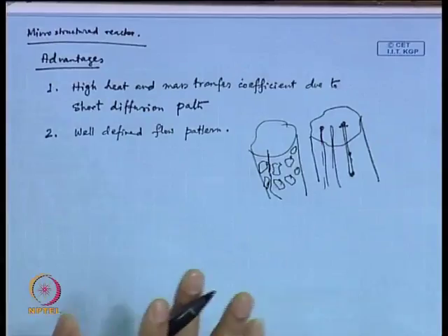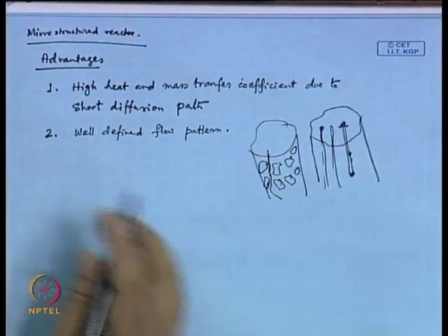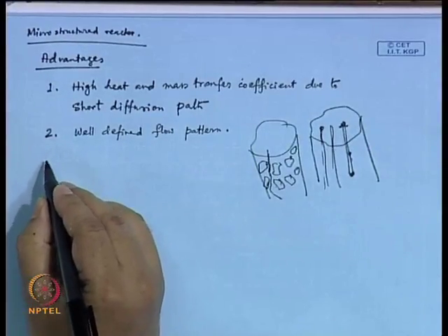And if there is too much of a reaction than what you want, there could be a possibility of thermal runaway. That means, if it is an exothermic reaction and too much heat gets generated, that you do not have any procedure to control, then the catalyst would be spoiled by that heat. So, these problems are there. In case of a microstructured reactor, you can get rid of these. Anyway, these are some of the issues that we already know probably.